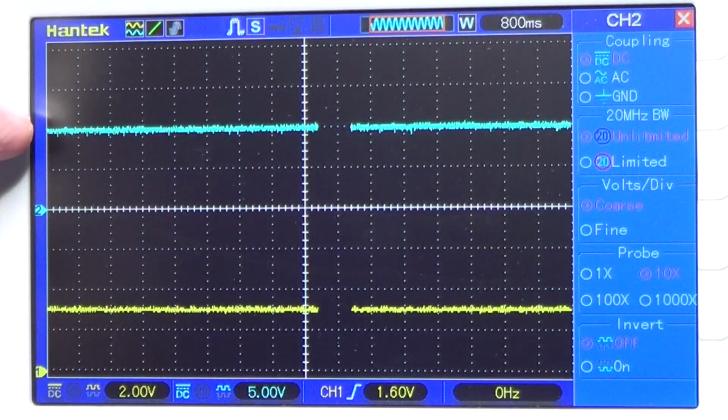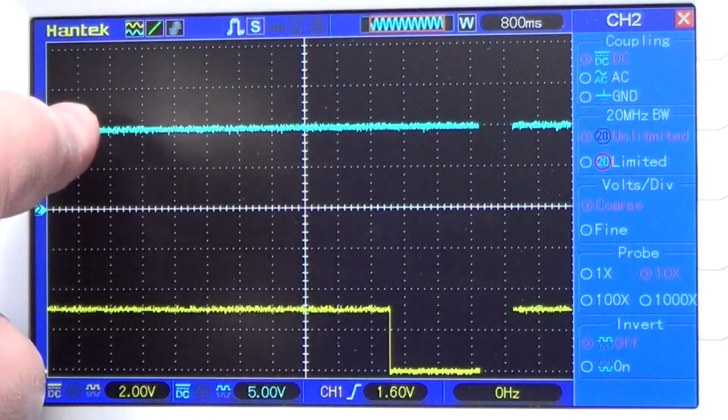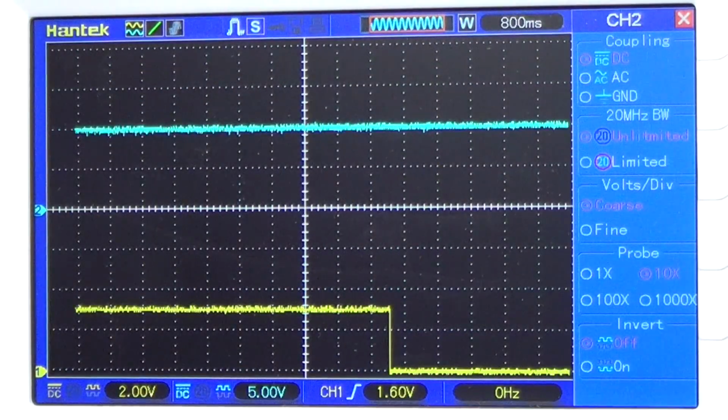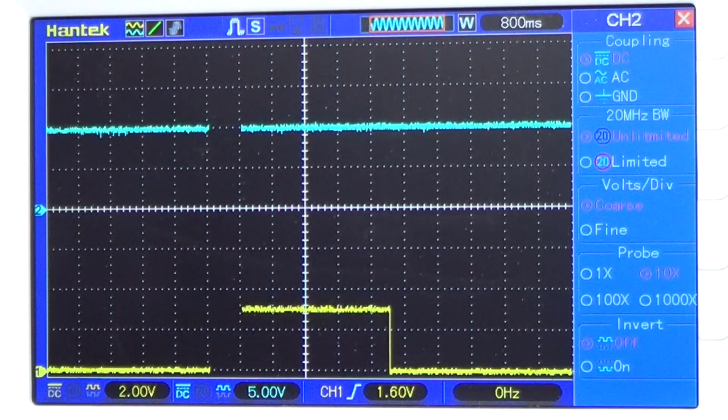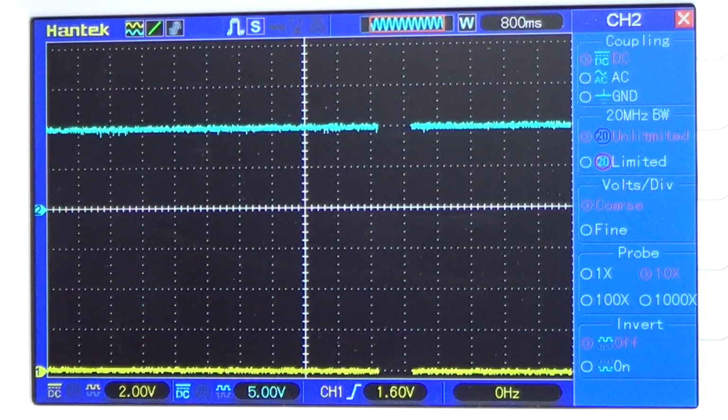Now I will remove the finger from the pad, and the note CV has gone to 0 volt, while the velocity CV remained in the same value. And in fact, I have taken the decision to change the velocity only when a new note is present, and leave it unaltered otherwise. We will see later if this decision makes sense. If not, it will be easy to change the code to make it go away along with the note CV.